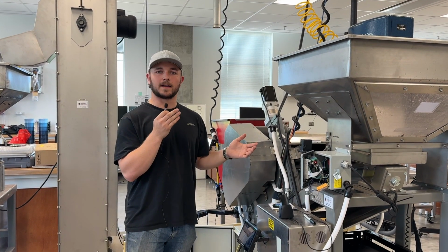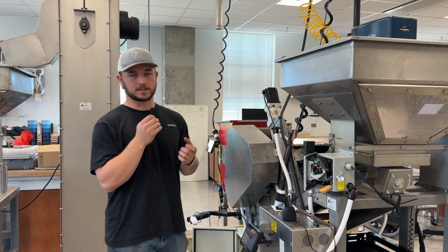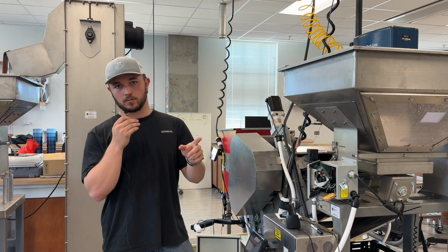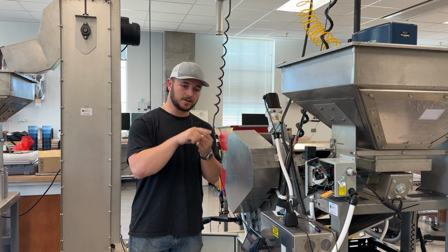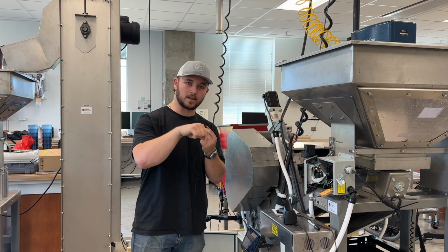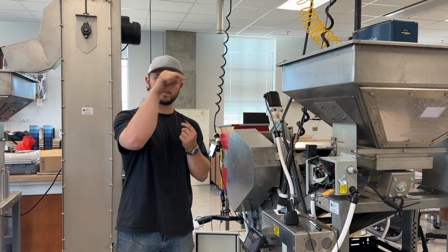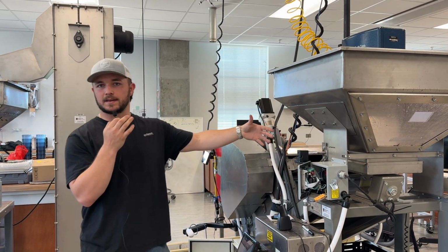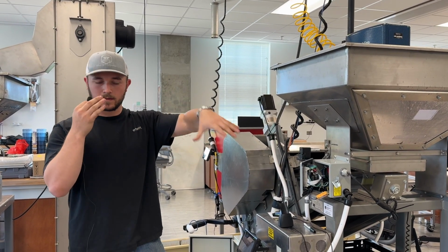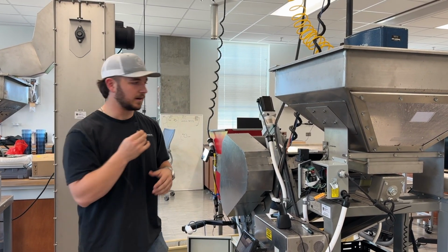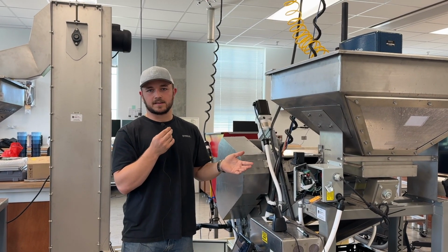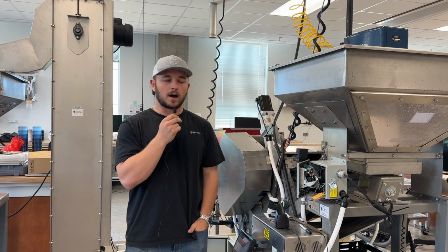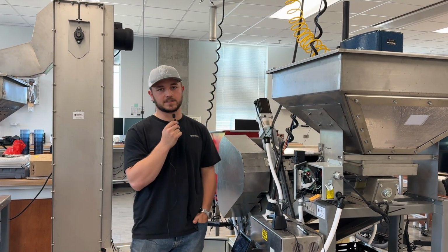We started off by trying to use a LiDAR sensor. A LiDAR sensor is essentially a laser, and we had it on a little motor, and it would spin and tell us the distance of each point it was measuring around the circumference of this motor. We tried to count the pecans by essentially making a point map of the surface of the conveyor. Unfortunately, that sensor did not spin fast enough, so we decided to move to an object detection computer vision model.